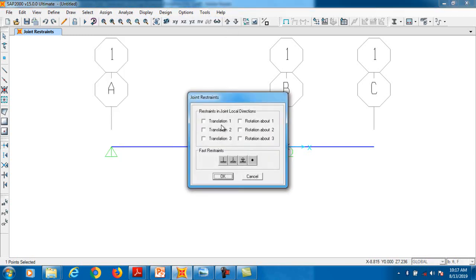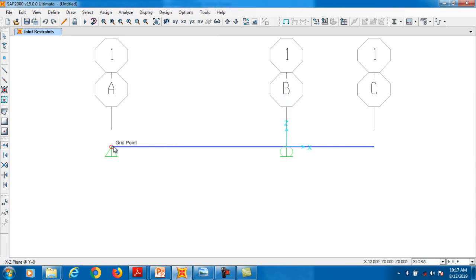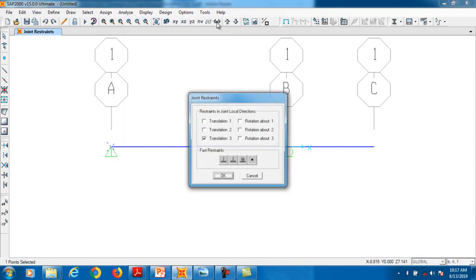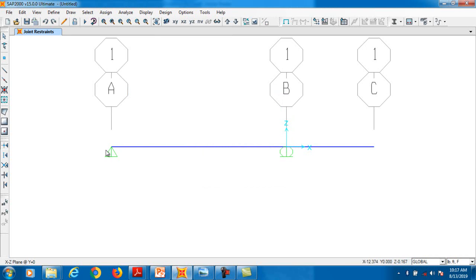One thing you must ensure is that you check these joints, whether it is a roller or not. You can see this is blank, which means this is just a point, not a joint. So there is a roller support, and you must check this joint as well. Just come and select the hinge. Clear? You must ensure these joints, because once you make changes there or delete the joints, it will make some changes in both these joints.